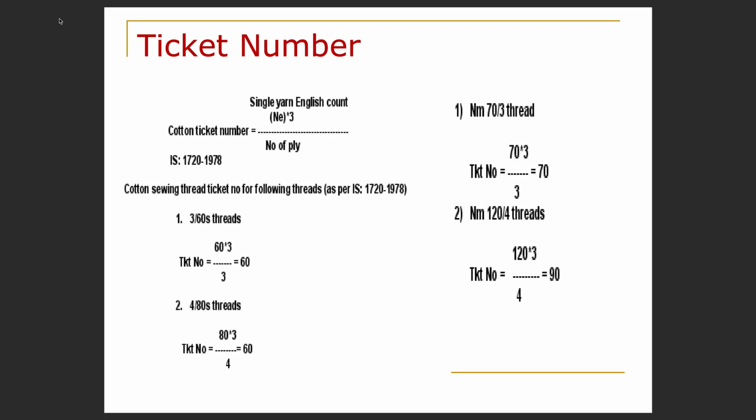So far we have discussed the relevance of studying the properties of sewing thread, and how important the sewing thread is in determining the properties of the seam and the final garment. It should possess good tensile strength and abrasion resistance. It should withstand the mechanical forces or stresses exerted during sewing. And then we discussed some of the constructions which are used in making the sewing thread, for example, spun, filament, monofilament and multifilament, and core spun or the core sheath type of sewing thread construction.